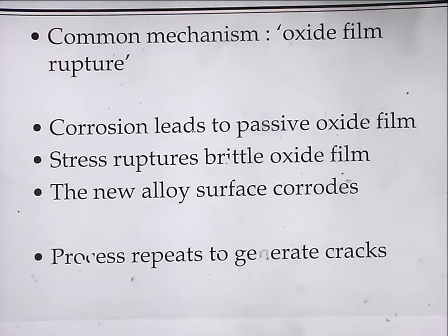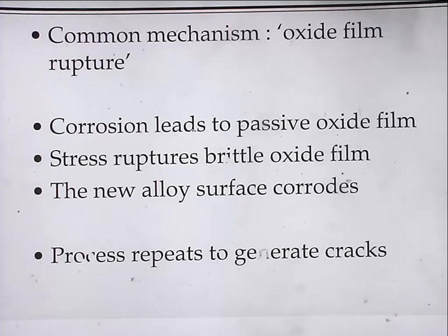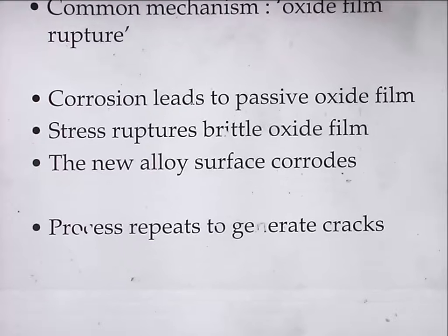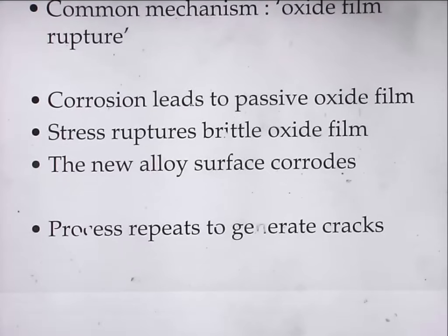So in stainless steels, you've got a chromium oxide surface layer, and oxides are generally not very ductile. They're brittle in comparison to the bulk metal underneath them. So if you apply a stress to the component, then the oxide film will rupture. It'll brittle fracture,